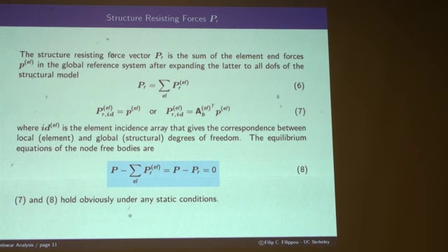We are writing node equilibrium, by the way, and the element resisting forces are the end-force vector expanded to address all the degrees of freedom, right?